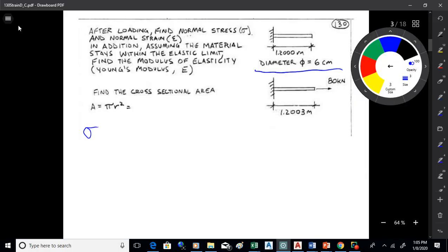Okay, so what you're looking at there is the force and the area to get the stress. The area, I think of it as being the area that holds the bar together, that resists the force, that absorbs the force. So that's going to be the cross-sectional area of the bar or the shaft, whatever you want to call it. And you just divide it in. It's a fairly straightforward calculation. So we're good with that. So just force over area, or P for load, sometimes we call it. So what we're doing there is we're taking the load over the area, like that.